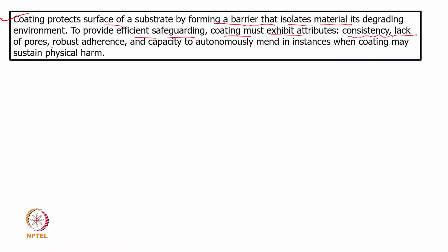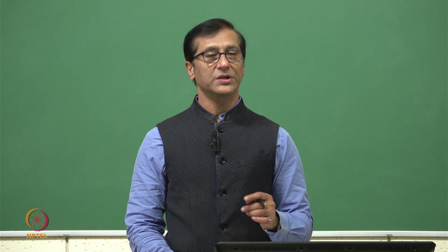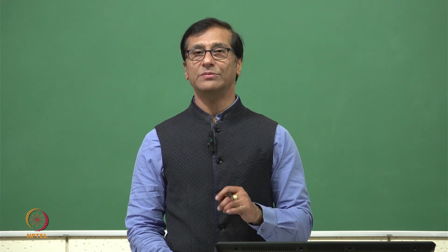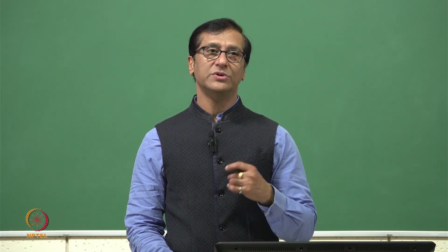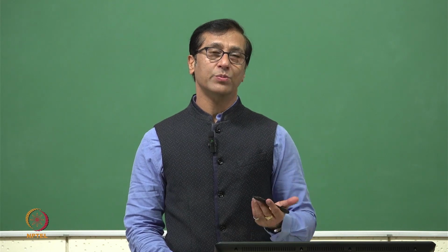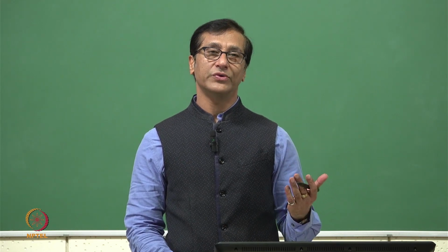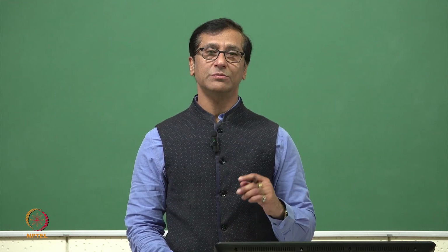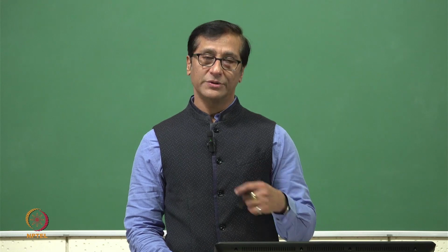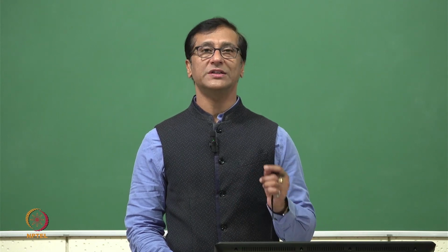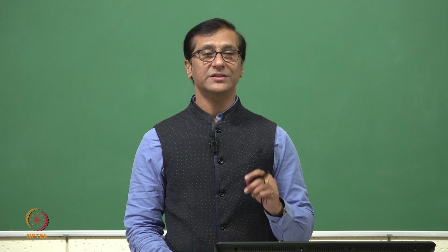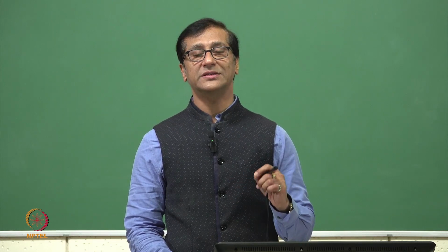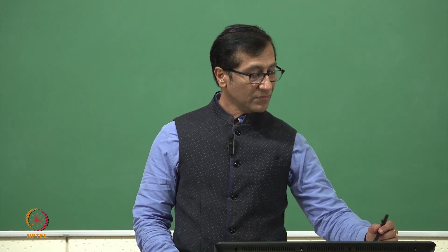Another one is that there should not be pores. We will be learning in lecture 16, if there is some sort of crack or some sort of pores, then there is a chance of tribocorrosion also. With tribocorrosion, the wear rate initially may be even smaller, but suddenly the component will fail. So we need to keep that in our mind. If there is no consistency, misalignment will come there. If there are pores, then there is a possibility of water or electrolyte getting ingress in there.